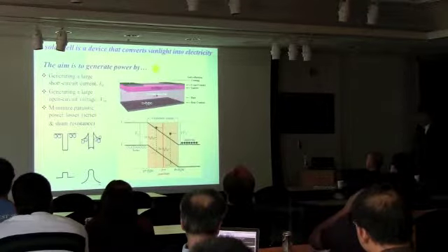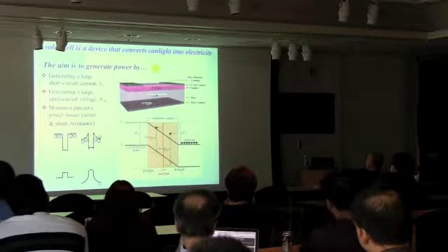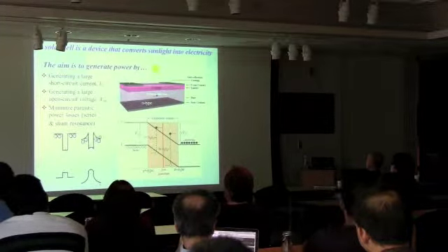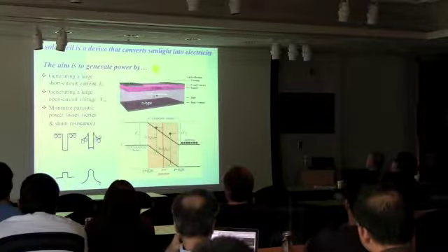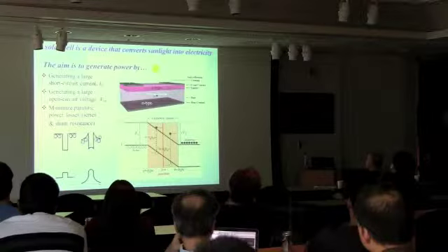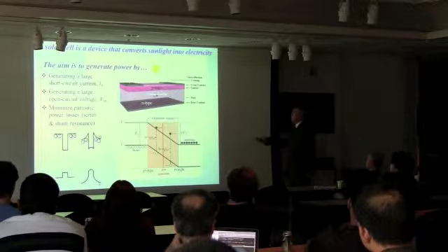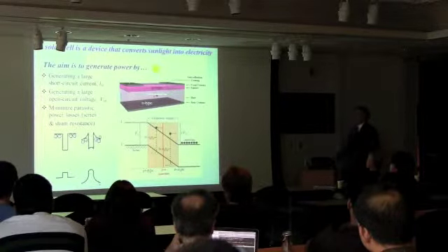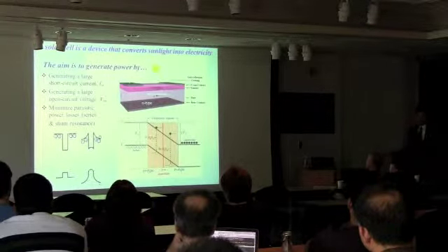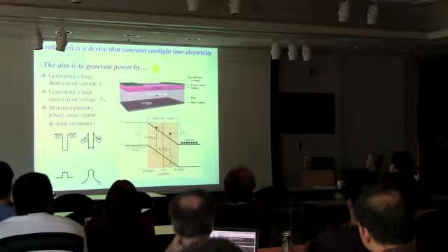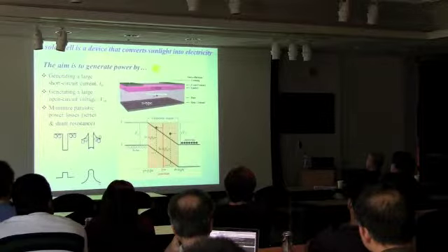So what is the principle now? When light is absorbed, an electron is taken from the valence band to the conduction band, and now we move this p-n junction or depletion region close to the top, like you see here, with light coming from the top. On the top you have p-type material, so light is absorbed, and the thickness of the material is regularly such that you absorb the light inside of the solar cell.